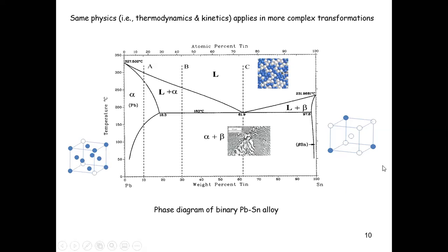But more importantly, in this alloy we talk about their atomic-level microstructure, and we have these regions, and these regions. What do we call these? We call them two-phase regions on the phase diagram, not necessarily solid solutions. In certain cases they are solid solutions, but they may have different types of phases. So this is the liquid plus alpha coexistence region, this is liquid plus beta coexistence, and this is alpha plus beta coexistence.